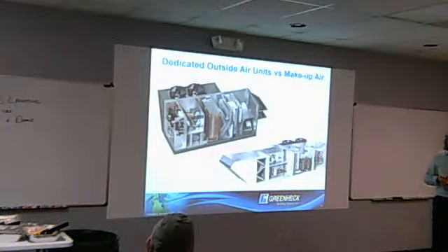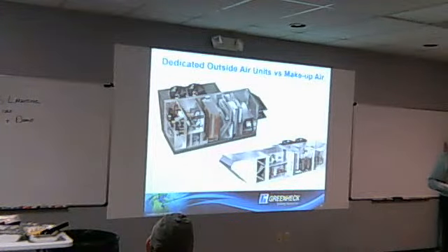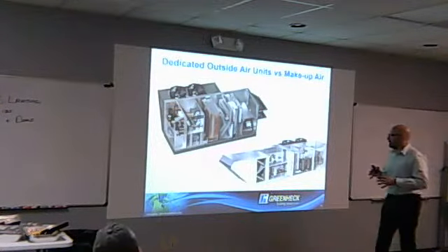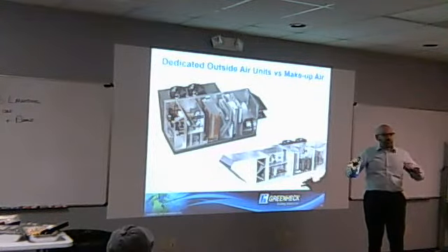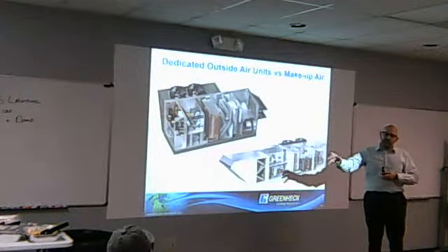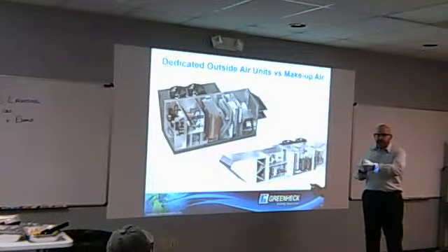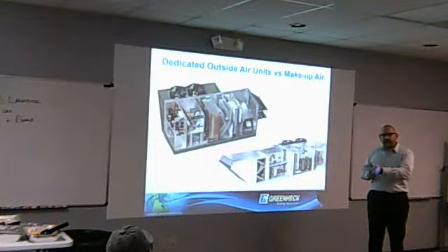Dedicated outside air unit. So we talked about this as a point. We've seen a big influx of this. And if I had to summarize in terms of a technology, it's decoupling the load on the space. So if we look at the outside air coming into a building, we need to dehumidify. And then you have the space that needs cooling.